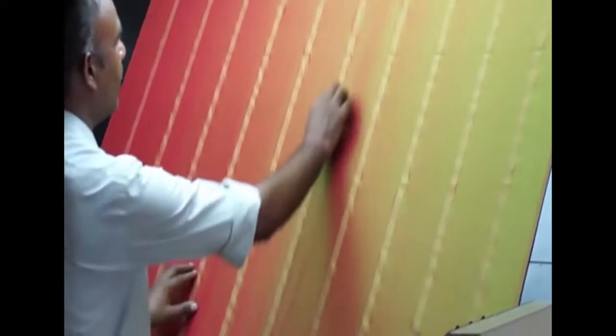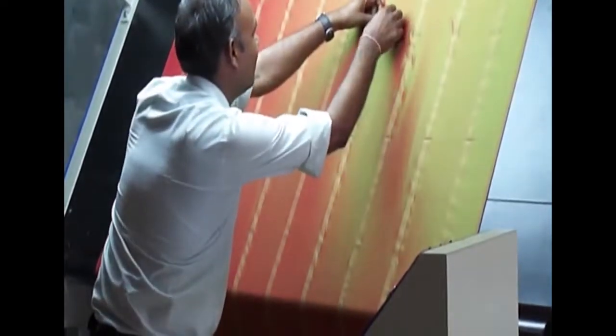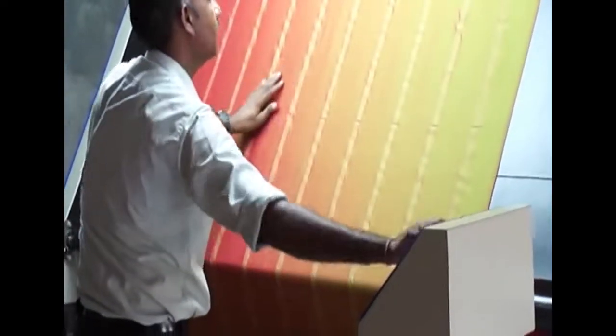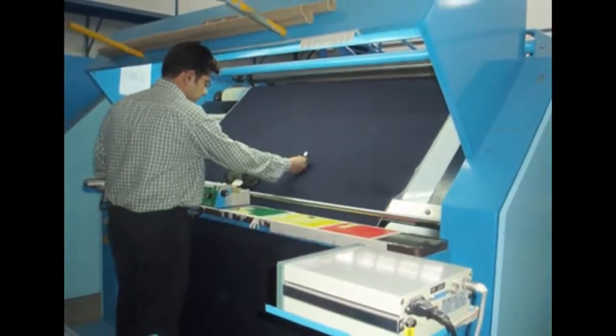Before the fabric is dispatched from the industry, thorough checking takes place to identify fabric faults, and subsequent action, if any, or correction should be taken care of. In garment industries, the major raw material is the fabric. When the bolts of fabric arrive at the industry, the first step in garment making is preliminary inspection of the fabric. Fabric should be checked in view of the quality required in the final garments. Checking the fabrics is paramount, as it avoids further problems associated with rejections of the final products due to noticeable defects. The extent of inspection is as per the agreement between the manufacturer and the supplier.